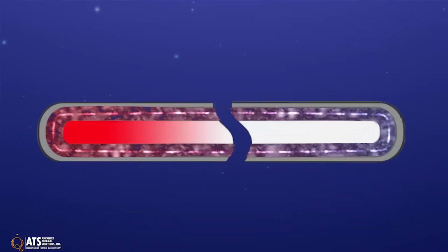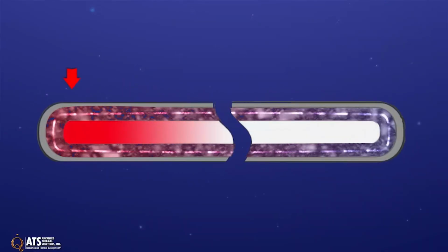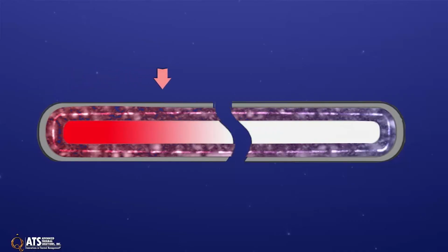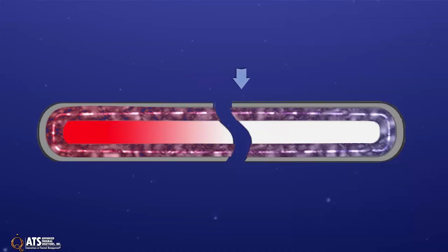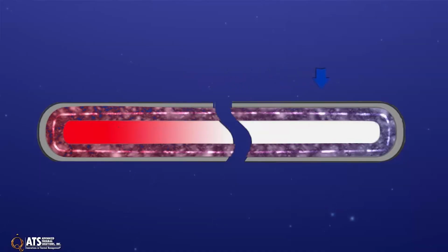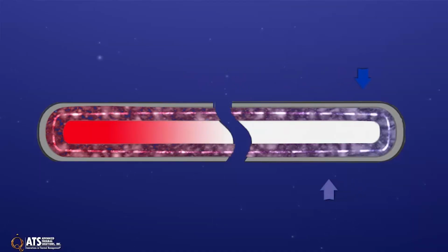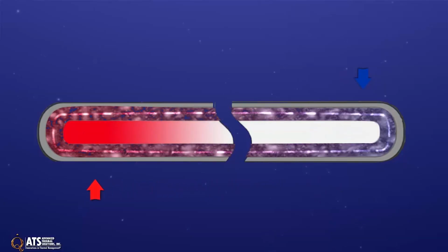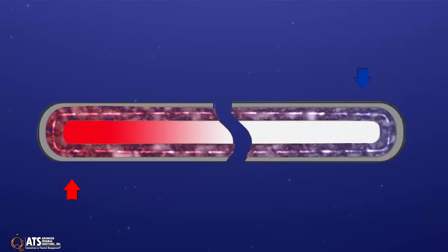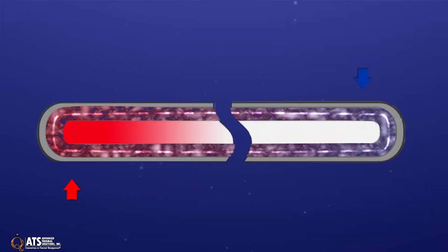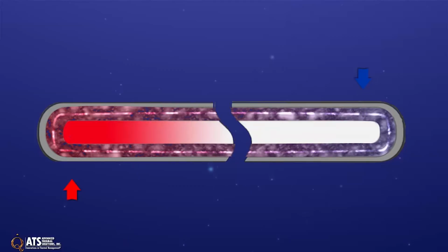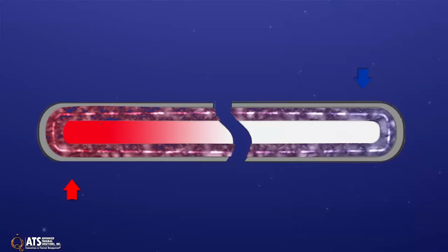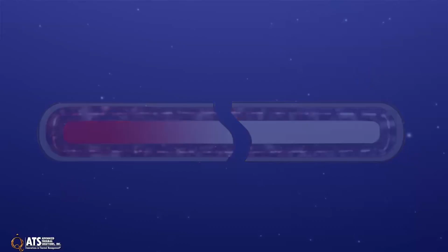Heat pipes work as follows. Heat applied externally to the evaporator section is conducted through the pipe wall and wick structure, where it vaporizes the working fluid. The resulting vapor pressure drives the vapor through the adiabatic section to the condenser, where the vapor condenses, releasing its latent heat of vaporization to the provided heat sink. The capillary pressure created by the menisci in the wick pumps the condensed fluid back to the evaporator section. Therefore, the heat pipe can continuously transport the latent heat of vaporization from the evaporator to the condenser section. This process will continue as long as there is a sufficient capillary pressure to drive the condensate back to the evaporator.